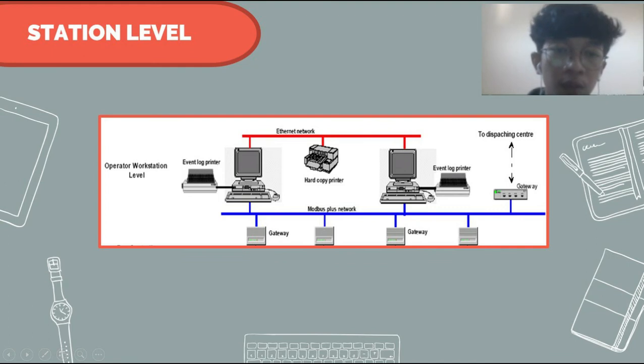In the event of a fault with the RTU, a message will be sent from the faulty RTU to the master station. A normal scan will experience a considerable delay, because the master station prioritizes the fault message and sets off an alarm so that the operator can take the necessary action as soon as possible.